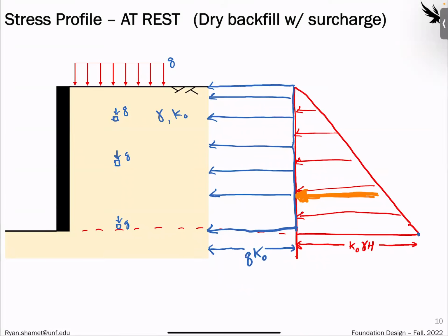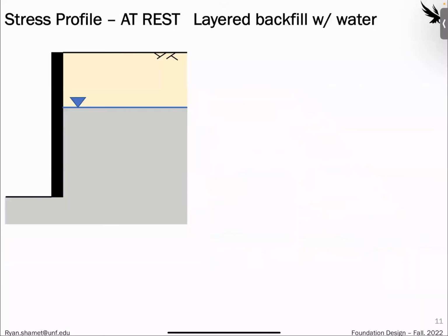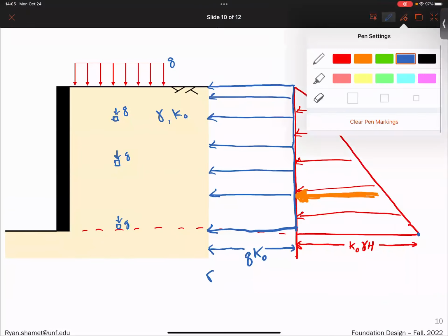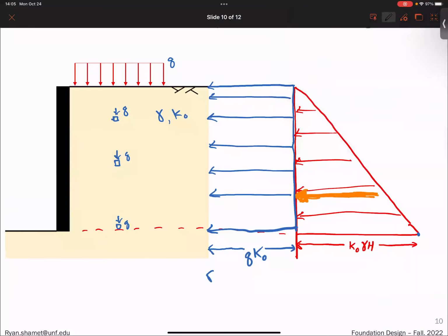Now when we're talking about structural design of the retaining wall, or the actual earth pressure on the retaining wall, we need to include both of these. So that's why what we'll show is this entire stress is equal to, we can bring the K naught on the outside since it's the same, the surcharge times the part of the soil.